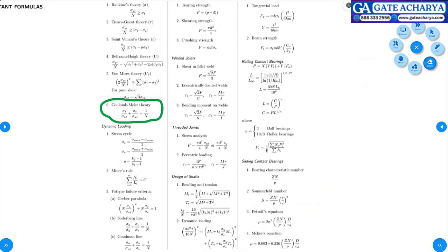They have asked in many interviews also, why for a material sigma YT is not equal to sigma YC. Why is it so? Tensile load means pulling away. Atoms move away from each other, lesser yielding. When you compress, they come nearer and nearer. At one stage, one will glide over the other.